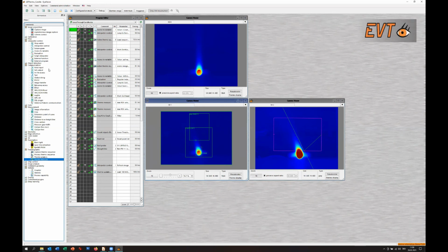Or if you want to control temperature, you can also use our temperature controller, which enables you to set a certain temperature and control that it's on that value. Or if you have resulting values which you need later anywhere in your factory, simply use the OPC way or direct Ethernet to send out maybe the temperature of the flame, or if it's still on.